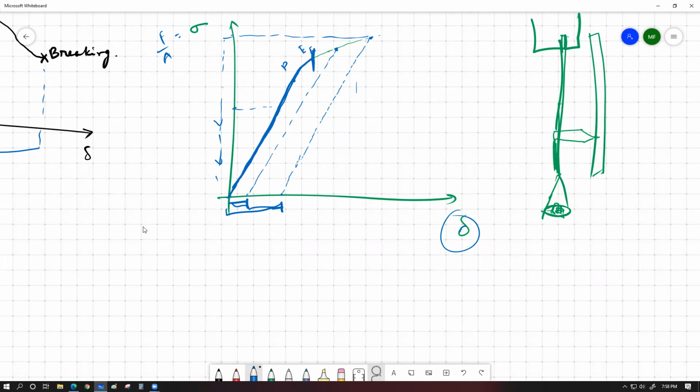Another thing is that if you have a permanent strain, then that is definitely going to have some permanent dislocation of the particles within the object, and that dislocation means that we would have actual displacement of some of the particles from their original position to a new position. That would require some work, and that amount of work, or elastic energy, or plastic energy, or you can say deformation energy, would be stored within the object as work done.